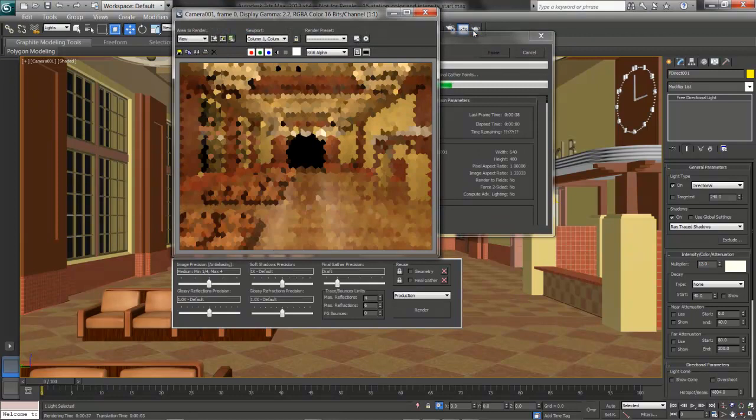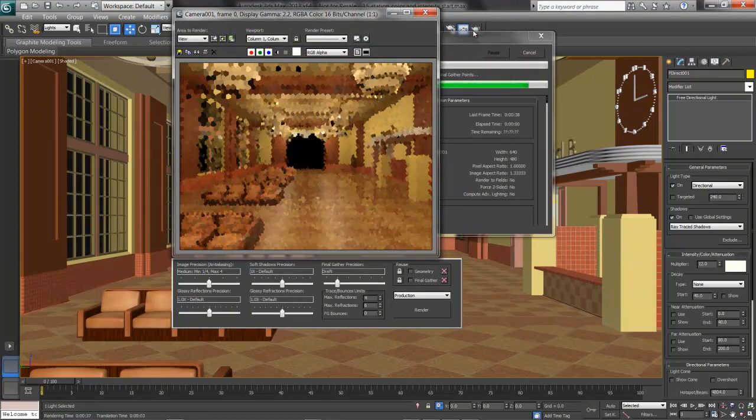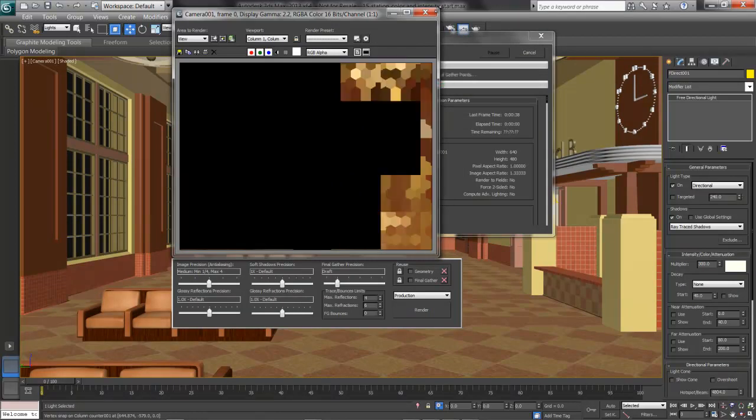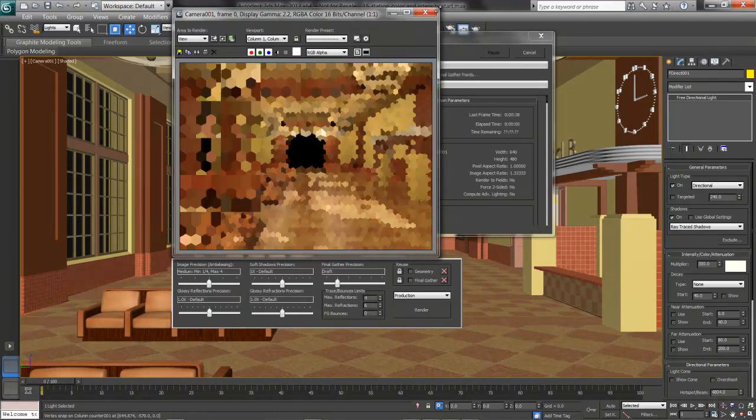As you can see with lights, there is some testing involved. Also, once we start dealing with photometric lights, our standard lights seem very dim until we crank them way up. It's working nicely, and I'm really starting to see the light come into the space, although it is a little yellow and I could adjust the materials. But first, I'll try to get this sun in. I'll try this multiplier a little higher, maybe 300. I'll try one more render and see if I get some light coming in there.